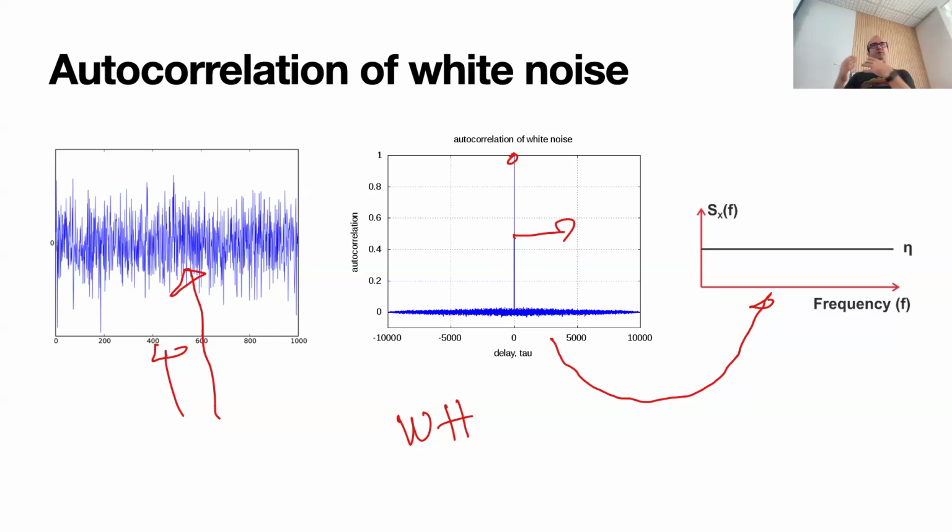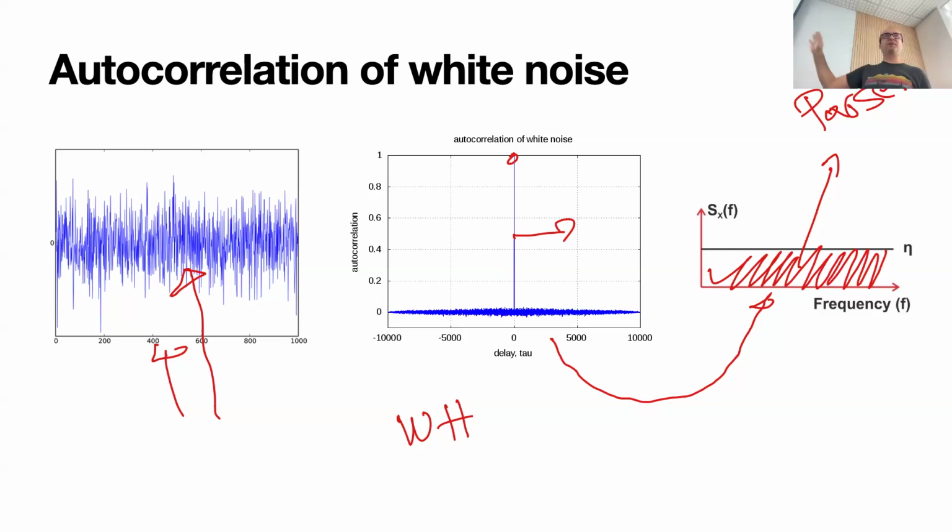When we try to generate such a signal, we need to put some energy in. The energy of a signal is actually the area under this curve. This relation is called Parseval's theorem. You can check it on Wikipedia, there is a derivation. This means that the integral from minus to plus infinity is infinite. It diverges. In essence, if we want to generate such a signal, we need an infinite amount of energy. And we don't have it.